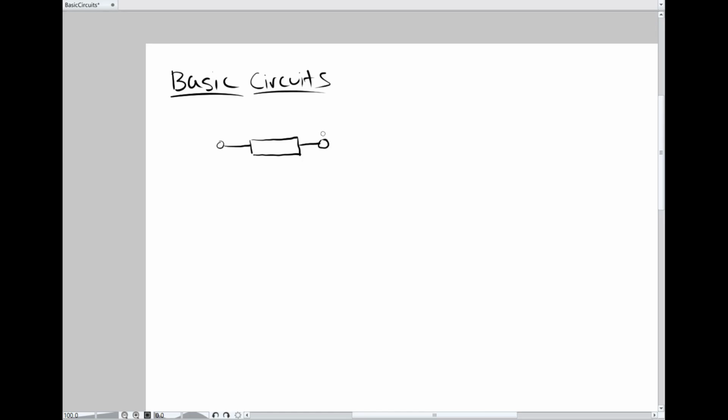However, we often throw around terms like Thevenin equivalent circuit, where we're describing a network that isn't closed unless we put a load on it. So a circuit doesn't necessarily always, in the way we use the word, represent something that's closed. It's an arbitrary interconnect of elements, implied that current can flow from one element to the next and branch between the different elements in the network.